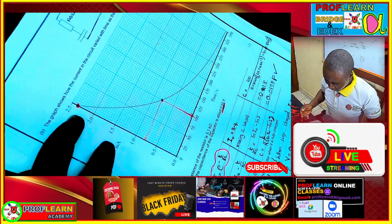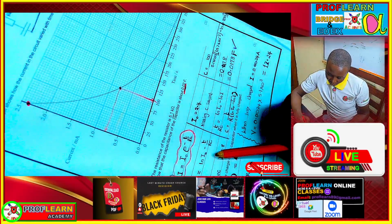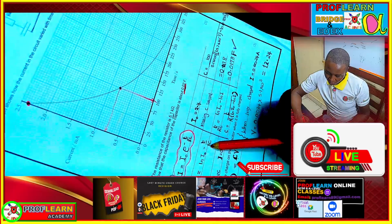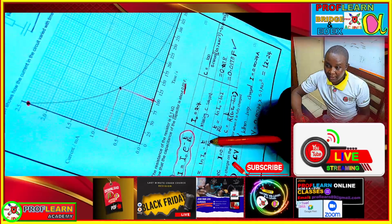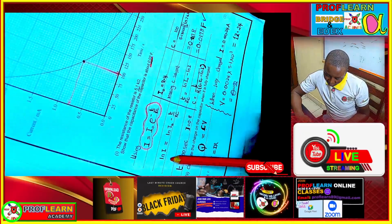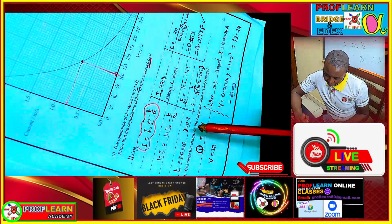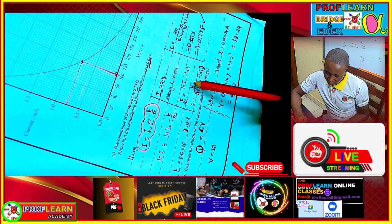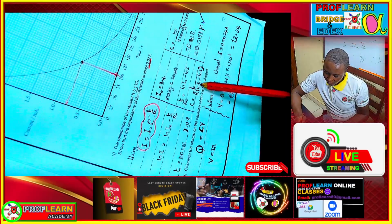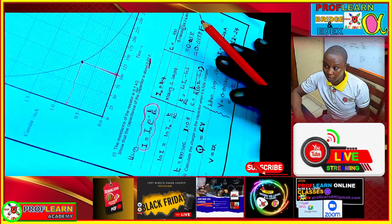Okay, and having that, we can say ln of I over I naught is going to be minus t over RC. So taking this to the other side and rearranging this equation, we are going to have C as t over R into ln of I naught minus ln I, after rearranging the equation that we were having there.